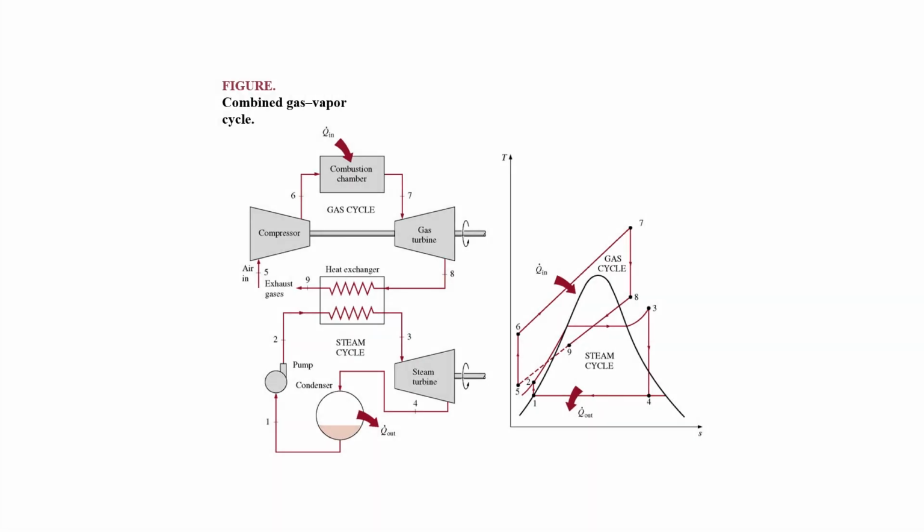So after all of this, we go to combined cycles. Combined cycles involve basically power generation from multiple cycles incorporated into one. A common example could be that you burn coal or you burn natural gas. It burns at a very high temperature, and that temperature might be much higher than the temperature you need for a steam power plant. So what you can do is you can burn this air fuel mixture in this combustion chamber, and then you can produce power from it, and this is still a very high temperature. For example, let's say this is still at 1000 degrees Celsius, or maybe 700 degrees Celsius.